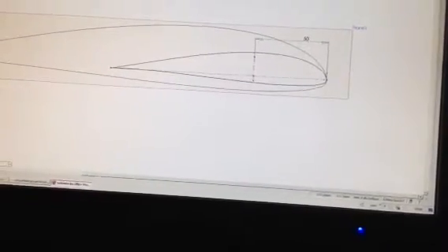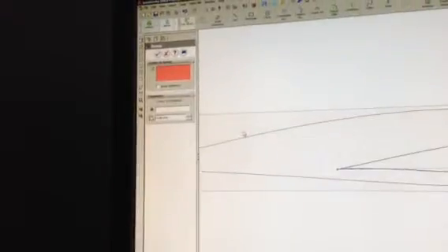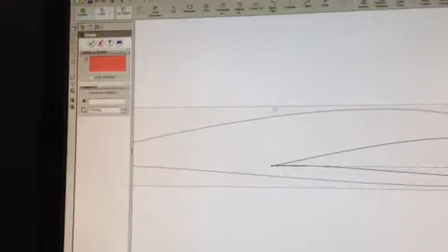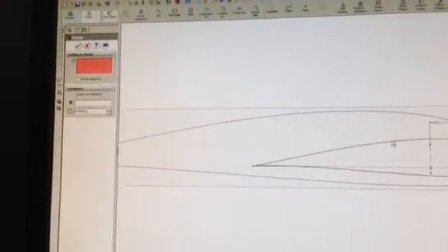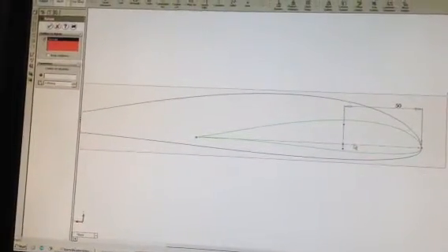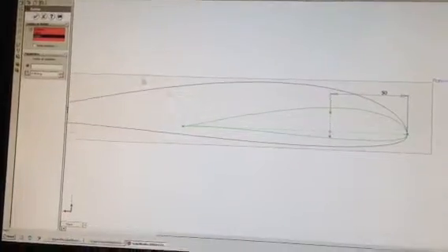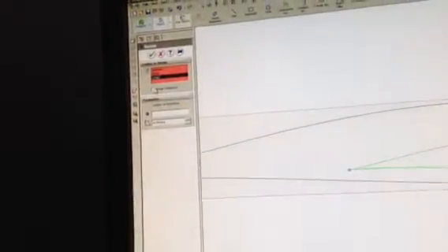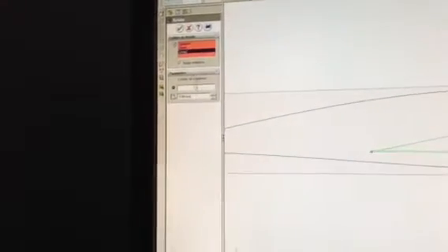Okay, so now we're going to rotate that sketch about this point. So I'm going to go Tools, Sketch Tools, Rotate. What entities will I rotate? Well, I want to click on the red area. I want to select the spline, and I might as well select the lines as well. Okay, so I'm going to keep relations. That means their relations to each other, as in if it's parallel or whatever. The center of rotation, so I'm going to click there to select, so it becomes red. I want to rotate it about that point. The angle, we said 10.